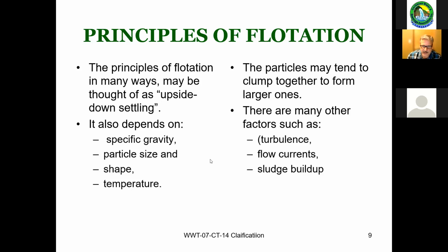Sludge buildup is huge, not only for unsightly or anaerobic conditions, but it also reduces the footprint of your tankage. If you're not having adequate sludge removal, it's building up in the corners, on the sides, or on the bottom of the tank, and it's actually changing the volume of your tank.